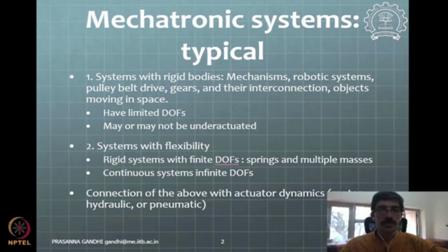One can handle this one or two degrees of under actuation by developing some kind of nonlinear controller. Under actuated systems control is a completely different issue to discuss and handle, especially in the nonlinear domain. In the linear domain, you still have some tools to deal with them; we'll see something in class.